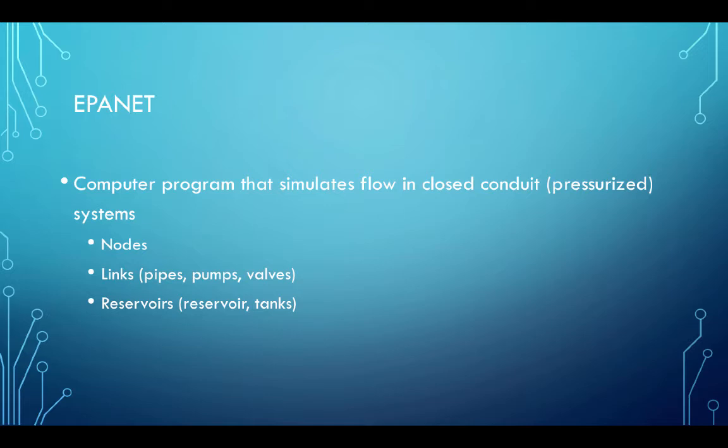Tanks, on the other hand, as we discussed earlier in the class, have water pool elevations that change with flow coming into or leaving the tank, and those are accommodated appropriately. There's a demand schedule, so when we're dealing with tanks that are going to drain and fill, we're no longer doing single steady flow runs. We're going to do a sequence of steady states, usually on an hourly time scale, and the program will compute the water level at the beginning of the time period, at the end of the time period in the tank, and in some other features, and that's conveyed to the program through something called a demand schedule.